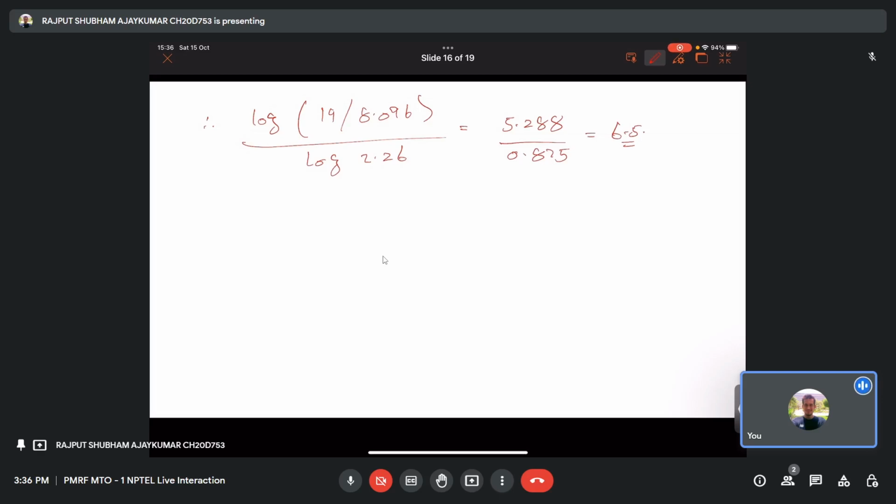And similarly, the minimum reflux equations are based on the invariant zones around the feed where the composition stops changing. So this is another term, like we already saw, for the multi-component distillation column. Another topic discussed this week was multi-component distillation with minimum reflux ratio. In order to determine an approximate minimum reflux ratio, we represent a multi-component mixture as a pseudo binary system. So I'll just write it down.